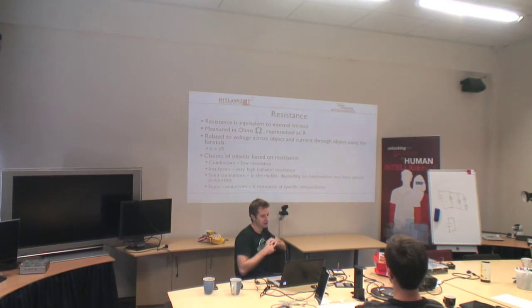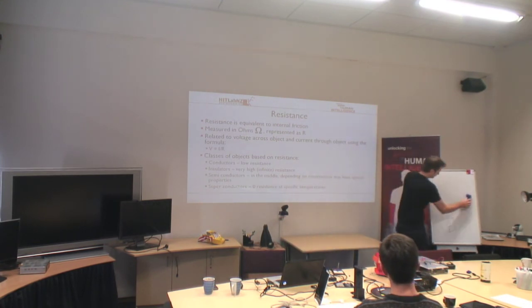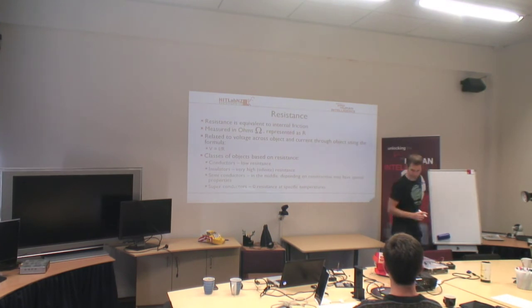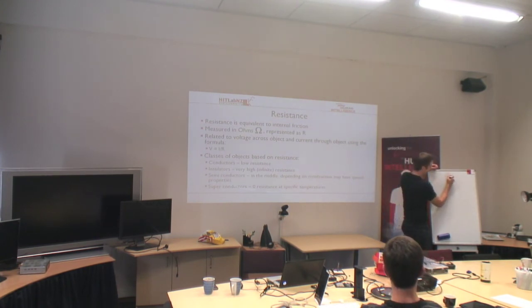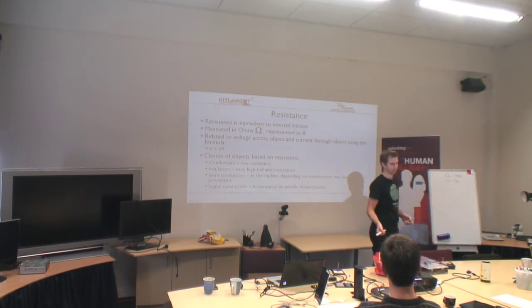So the voltage which is used by a certain load, so if we have a light bulb, will depend on the current multiplied by the resistance. So if we had that 330 ohm resistor before, well, actually we'll do it the other way. We had one of these resistors down, this one here is 330 ohms. So we have our resistance equals 330 ohms. Then we have our voltage is equal to 5 volts. So we know there's 5 volts coming out of the Arduino and then going to 0.